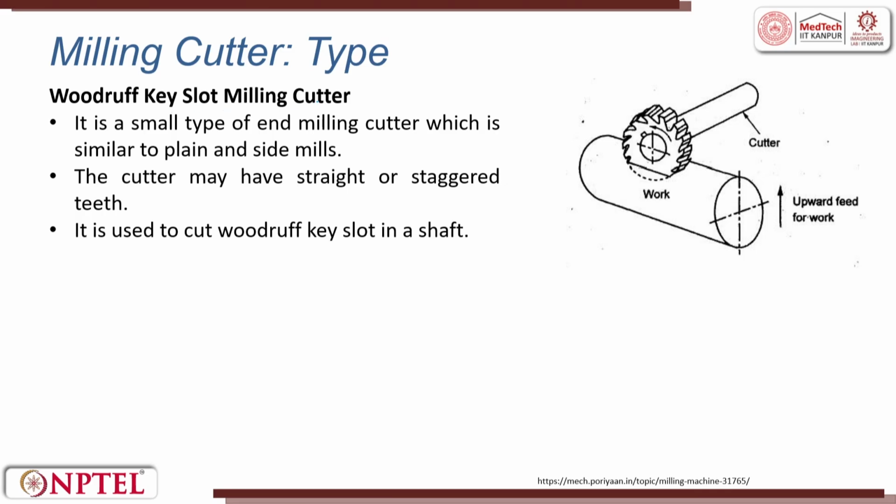Woodruff key slot milling cutter. It is basically used to create a key slot, so that you can place a key for locking. It is a small type of end milling cutter, which is similar to that of a plain or a side milling cutter. The cutter has straight or staggered teeth. They are used for making key slots in shafts.